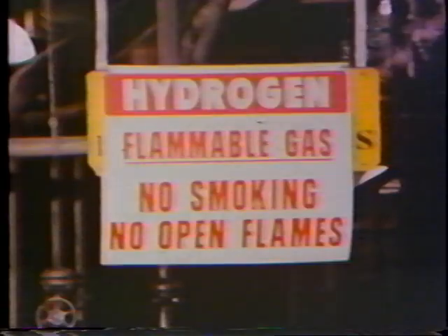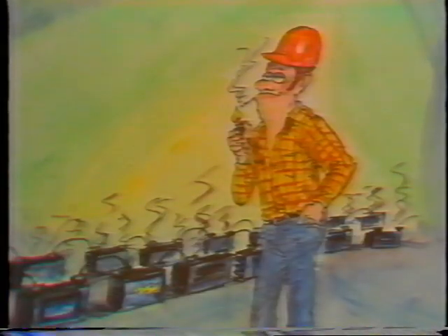Finally, we come to the part about batteries that I hope you'll remember best. I'm talking about the safety precautions associated with handling or working around batteries. I said earlier that hydrogen gas is released from a battery as chemical action takes place, and that this gas can be an explosion hazard. For this reason, you must not smoke around batteries. Also, make sure that there are no open flames or sparks in the area. They could set off an explosion.